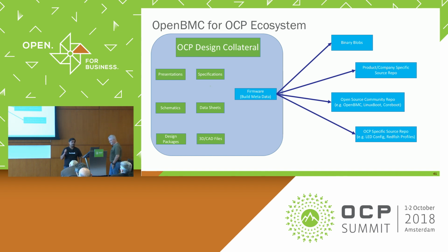If you take a look at today's firmware, as I said before, CPLDs, bridge ICs, BIOS, VRs, etc. Some of these should be available as binaries, or some people might say, my company has this source code, you should be able to build it. It's not yet open source, but you can build it, so it should support that model. Or it could be completely open source community projects like coreboot, LinuxBoot, or OpenBMC. So people should be able to say, just go here, this is the makefile, build it, give this platform name, and it should build and generate the binary for you.